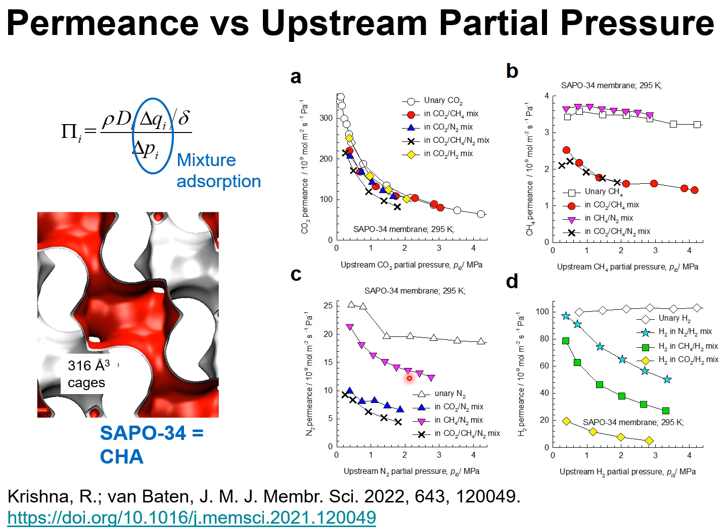If we consider a mixture of nitrogen with CO2, the lowering in the component permeance is still greater, and you can see there's a factor 2 to 3 reduction in the component permeance of nitrogen in mixtures with CO2. And this is for a ternary mixture of nitrogen in a mixture of CO2 and methane. We see a significant reduction.